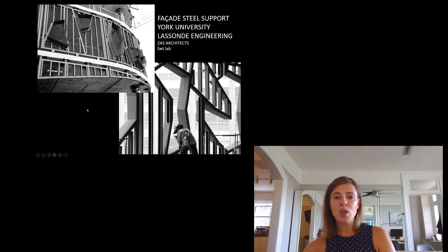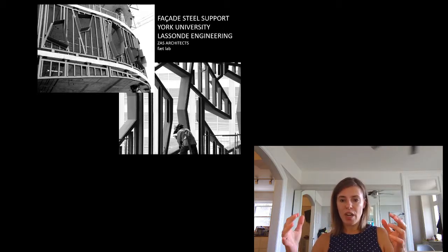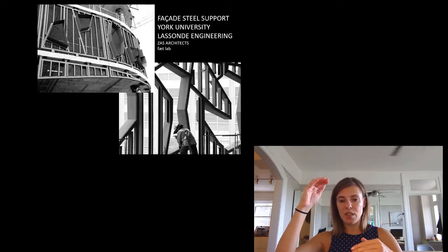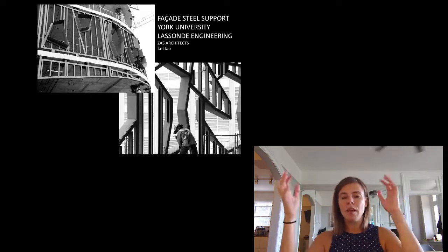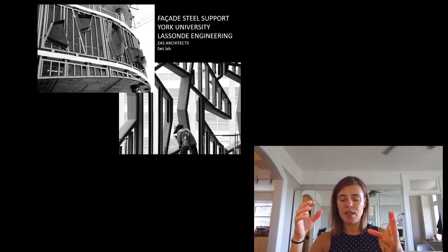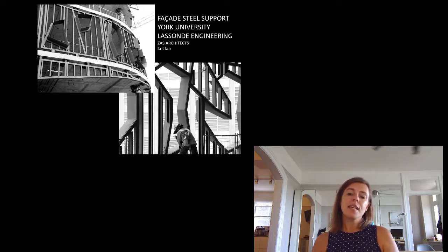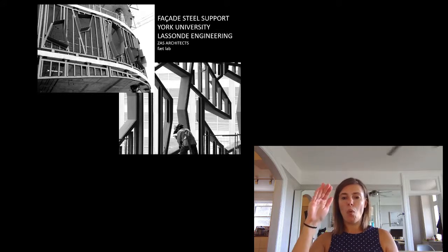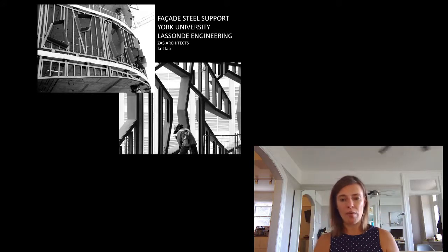They also had the added difficulty that normally in a building, you build the concrete structure, you measure everything for as-built site conditions, you go back, you fabricate the steel frames. You come back, insert the steel frames, measure everything for the as-built conditions, and then go back and fabricate your glass. This was on such a tight timeline that they needed to be building the concrete structure while they were fabricating the steel, while they were fabricating the glass, which meant everybody had to know everybody else's work was absolutely perfect. And nobody was really willing to take it on, and I guess I was crazy enough to say yes.